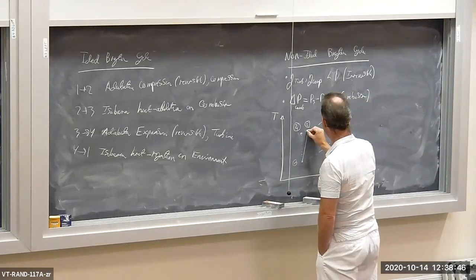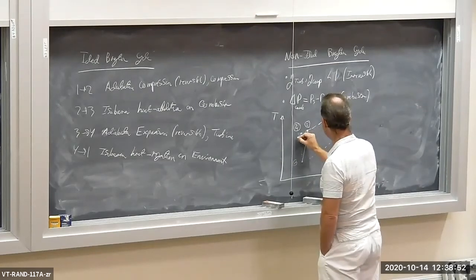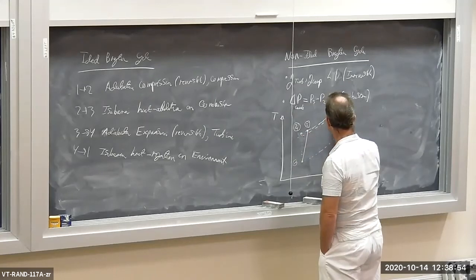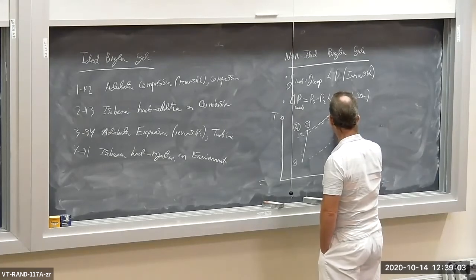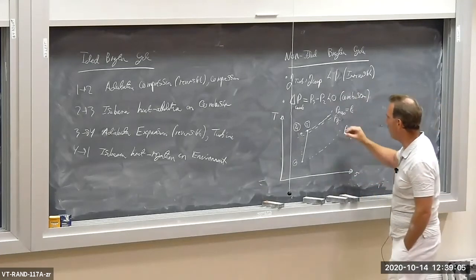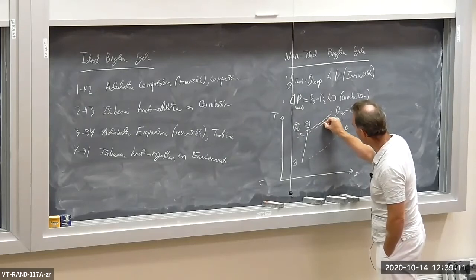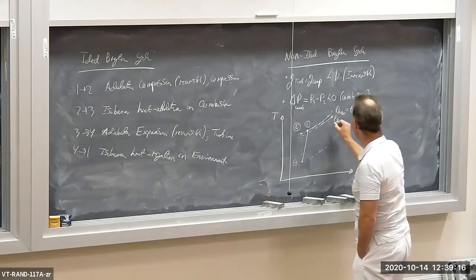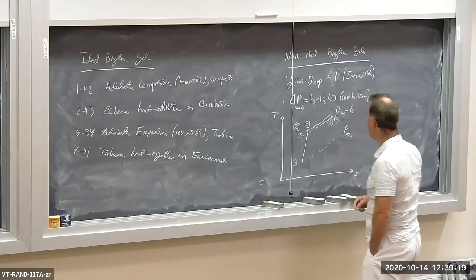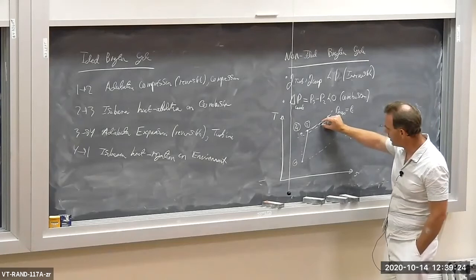Then we have maybe a pressure drop. So here's P max is equal to P2, and here I have P3. There's our P3 isobar. So we have a pressure drop. We start off at a high pressure P max, and then we drop to a lower pressure in the combustor. And so this is state 3 here. There's state 3. Delta P across the combustor, delta P.